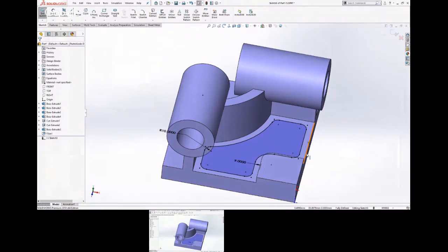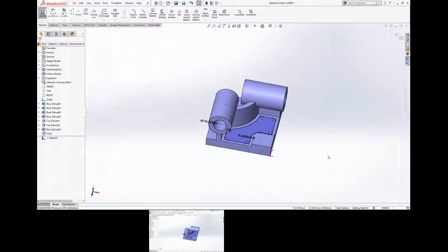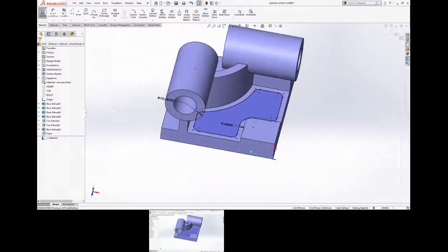Okay. So there's, again, a few different ways to do this. You can offset that sketch a few different ways. Because I've clicked through and I know that it doesn't change, I'm just going to simply cut it down 20 millimeters, okay? Because in this case, I know it'll save me a little bit of time. We've done some really complicated extrudes where it offsets from a surface, then offsets the other way and cuts through it. But in this case, just type in 20. It's simple that way. So again, as long as you know that's not going to be affected, then you can do that.